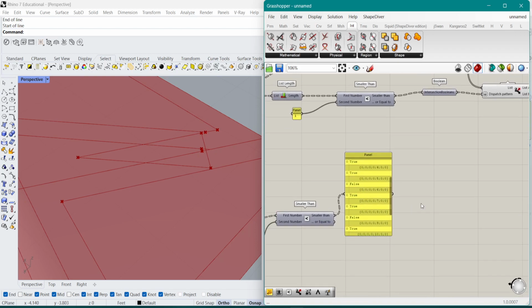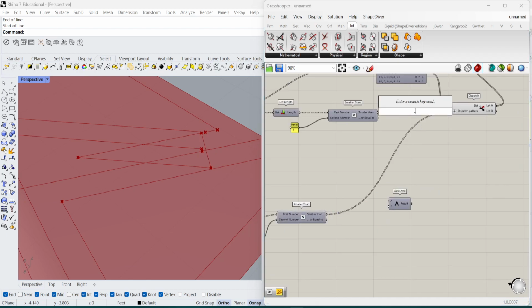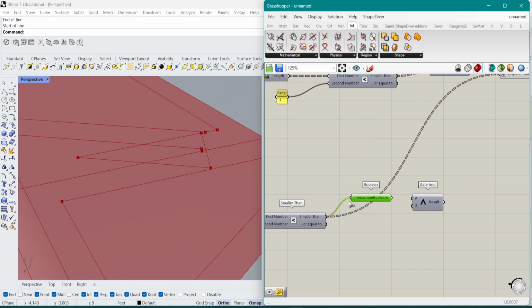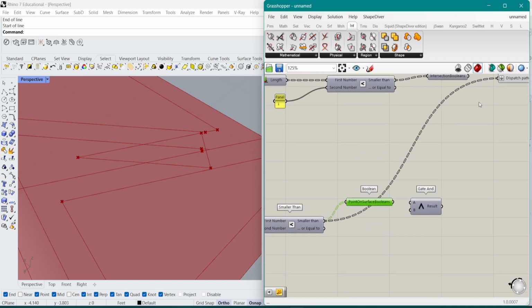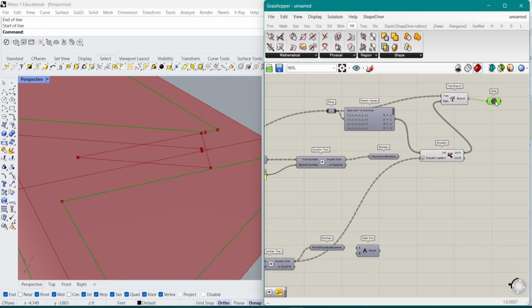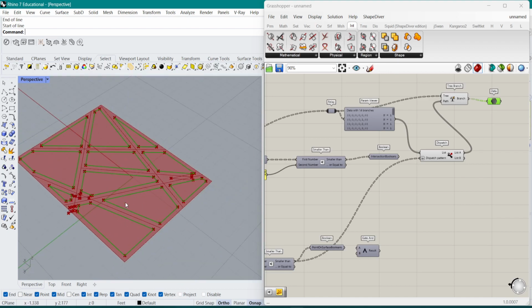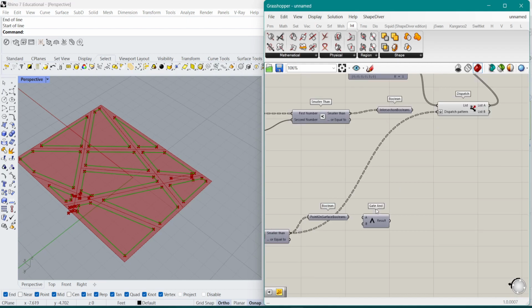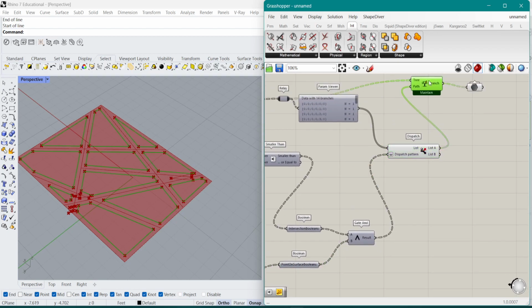And then I have the true and the false values here, and I'm connecting them together. So I have the values here, for example, in the dispatch pattern. If I'm just going to copy this here, and we name it intersection, and here we name it point on surface booleans, and we put it in the dispatch pattern thing as well. And now the result should be, okay, cool, I have now this one removed. And those ones actually in a way as well, so that kind of gets doubled. But what I want to do is basically have them work together. So I put those two together like this in an AND gate, and this will then also work rather fine.